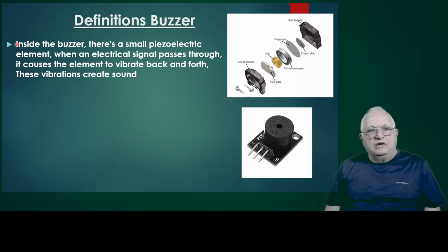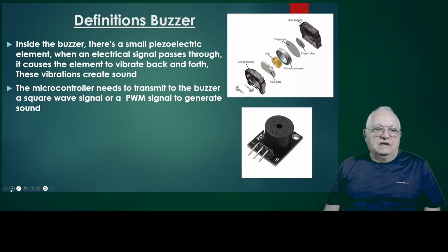So inside the buzzer there is a small piezoelectric element. When an electrical signal passes through it, it causes the element to vibrate back and forth. This vibration creates sound. The microcontroller needs to transmit to the buzzer a square signal wave or a PWM signal to generate sound.